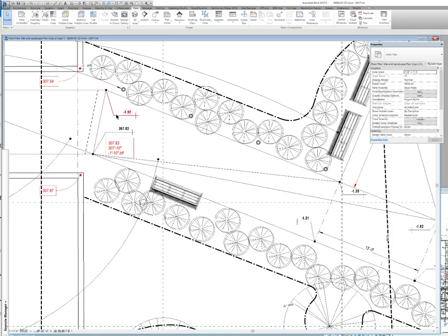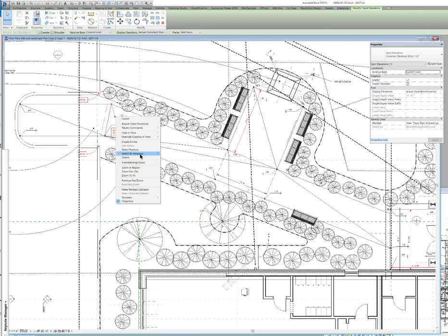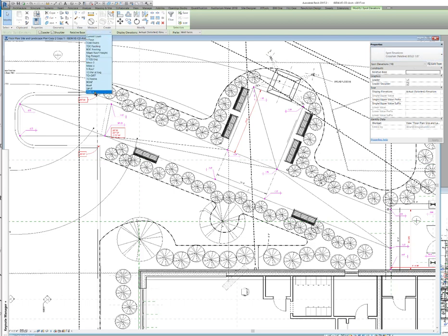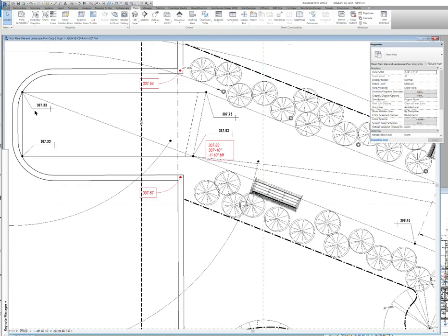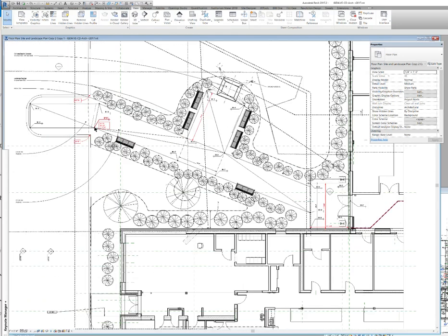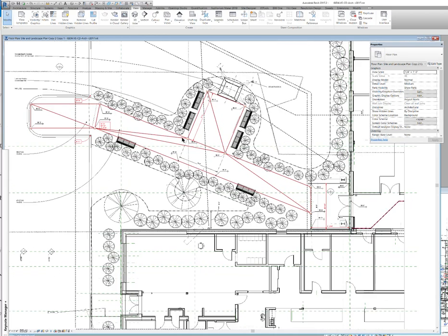But the helpful thing to do is now that you did all this and you click these all over the drawing, just right click it, select all instances visible in view, change this to relative to base 0, and then the whole plan is done. Everything is detailed up. Super slick. And then also if I'm waiting for additional information, let's say, and I just change these points, if I had to push things up or down, you can kind of come back in and do that. That's it. Not that hard. Note to self.